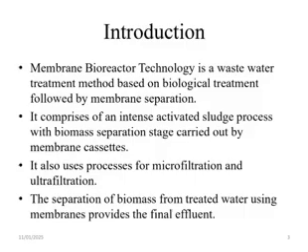As we can see here, MBR or membrane bioreactor technology is a wastewater treatment method based on biological treatment followed by membrane separation itself. It mainly comprises an intense activated sludge process with the biomass separation stage being carried out by the membrane cassettes which are located in the bioreactor itself. It also uses the processes of microfiltration and ultrafiltration. Finally, the biomass is separated from the treated water using the membranes, and it provides us with the final effluent. Now, we will move on to the working mechanism of the membrane layer itself.